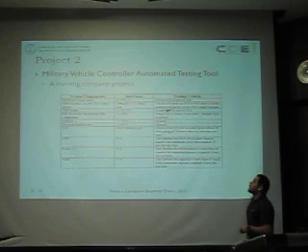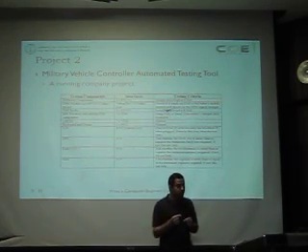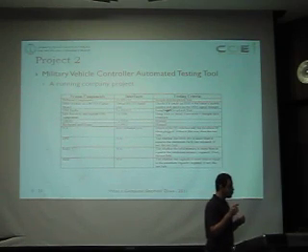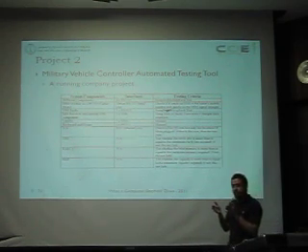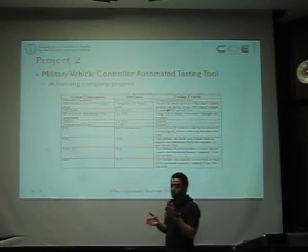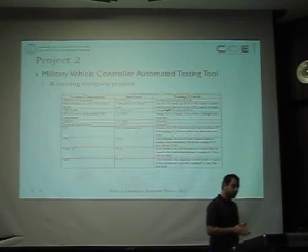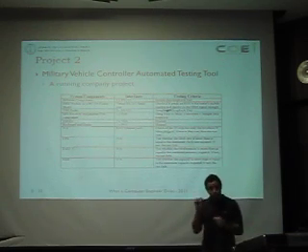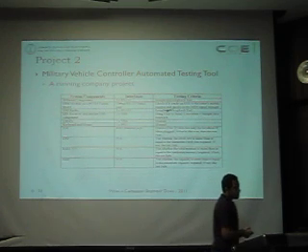For example, we can test the RS-232 by using a loopback, where we can send a set of characters in an order, and we see if we get the same set of characters in the same order, then the RS-232 is functional in this way.